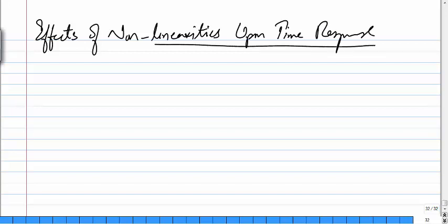It's very important: you have to look at the response of the system and identify how the response looks. If you remember, we discussed different nonlinearities that we have in the system. The first one was saturation.